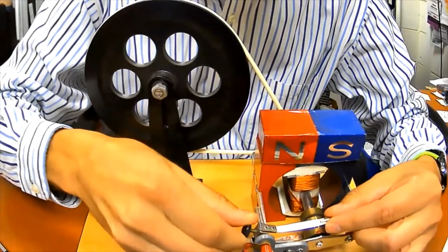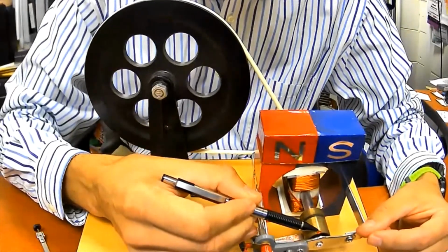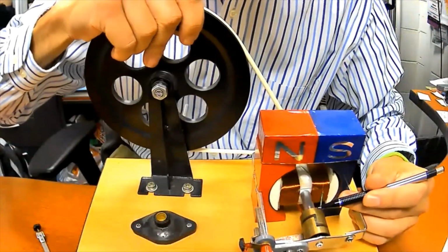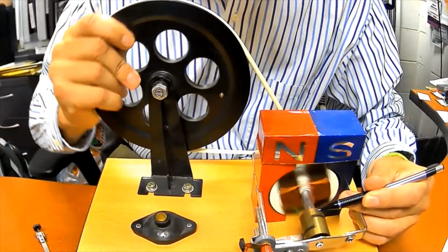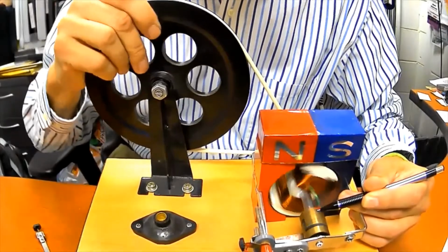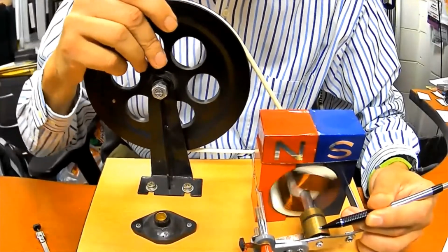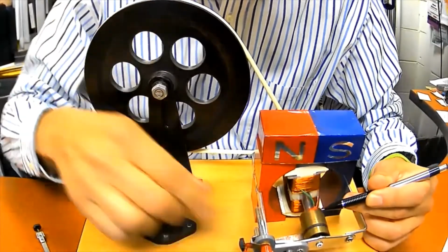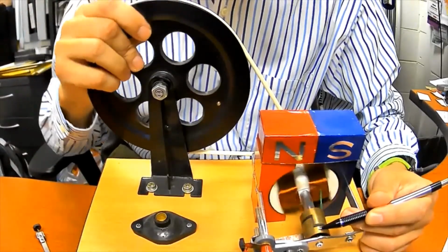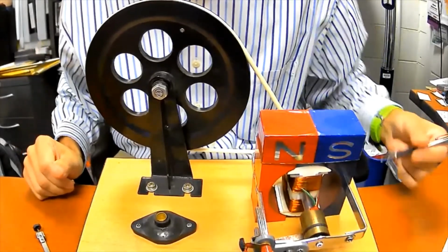So I'm going to move this again so you can see what's going on. So if I have one brush all the way over on this side of the device, and the other brush is all the way over on this side, notice that this brush is always connected to the same side of this device. So it functions like a slip ring. And this other brush would be over here, and it's always connected to the other side of this output device. So if I had one brush over here, say the bottom brush is over here, and the other brush is over here, then this would function like an AC generator because this is functioning like a set of slip rings, all right?